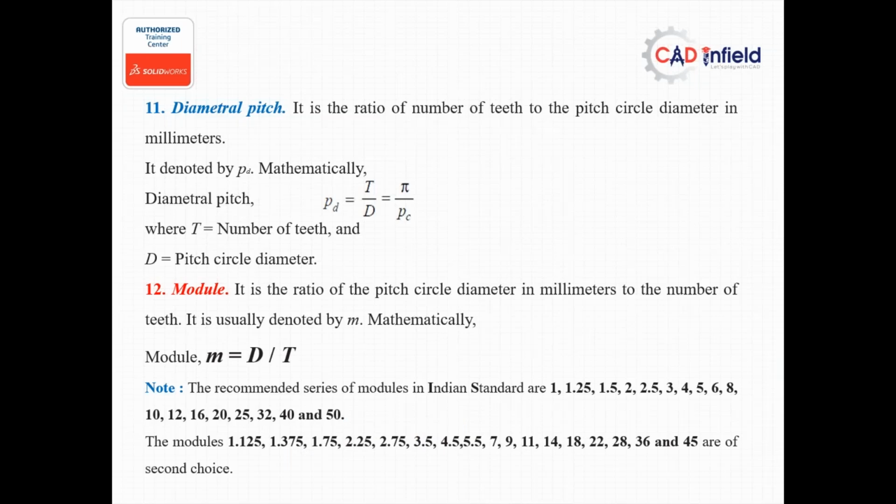We have a module, m is equal to d by t. I will give you one tip. Maybe in my calculation we will get it. For any successive engagement of the gear, I repeat, any successive engagement of the gear, your module must have to be the same.